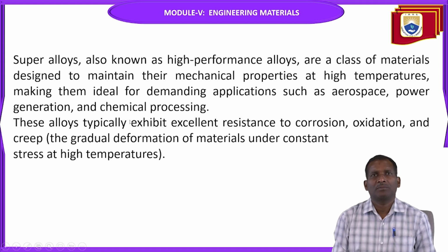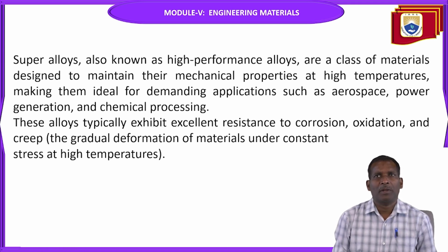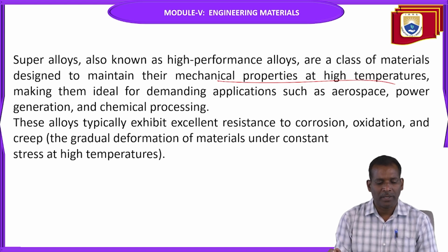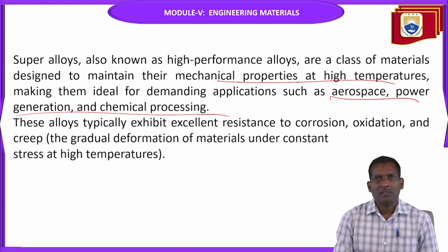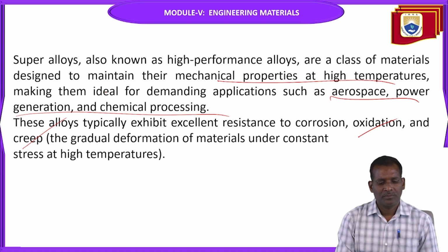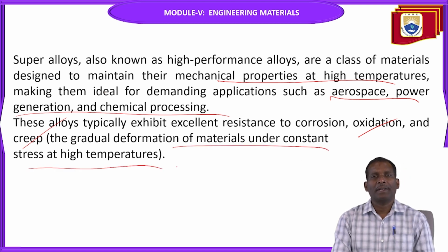Next, superalloys. Superalloys, also known as high performance alloys, are a class of materials designed to maintain their mechanical properties at high temperatures, making them ideal for demanding applications such as aerospace, power generation, and chemical plants. These alloys typically exhibit excellent resistance to corrosion, oxidation, and creep, the gradual deformation of materials under constant stress and high temperatures.